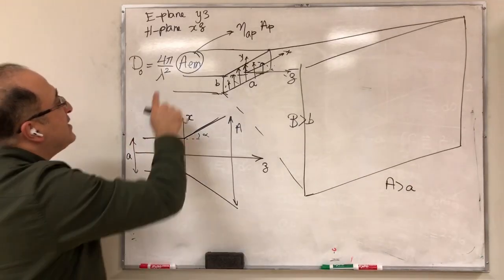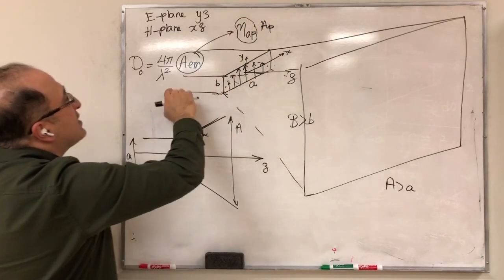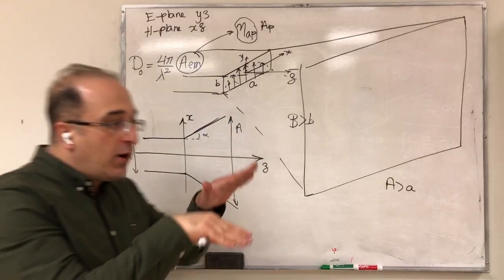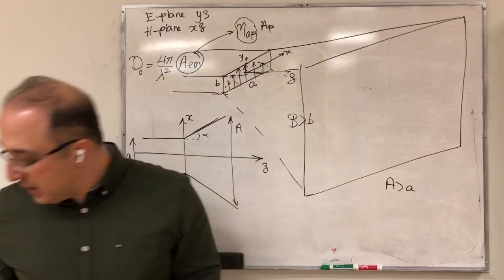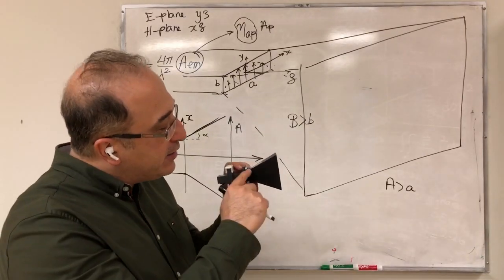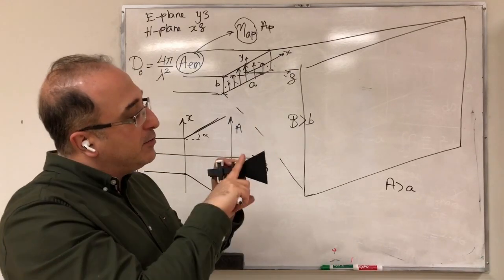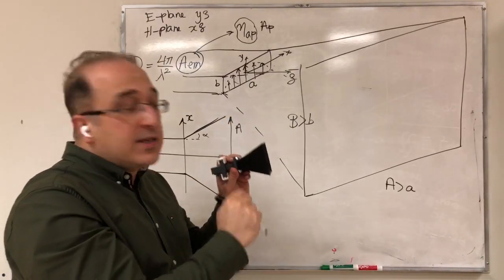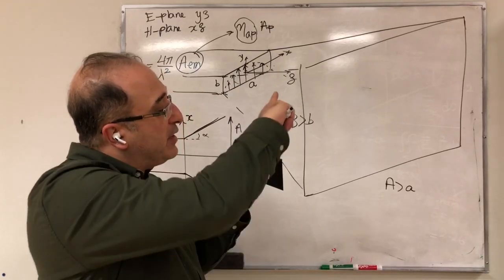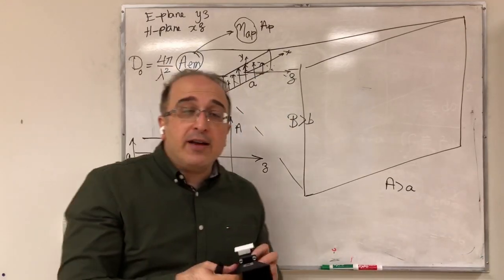So you clearly see here that if you ignore this for a second, your maximum directivity relates to your physical aperture. So you might want to go very sharp out. But then the question is, if that's the case, why did they choose this specific angle? Why didn't they go like that? Because they could have gone like this and have a much sharper transition. And with this length, you could have a bigger aperture. Go here and go here, and now you have a bigger aperture. Why is that not the case?